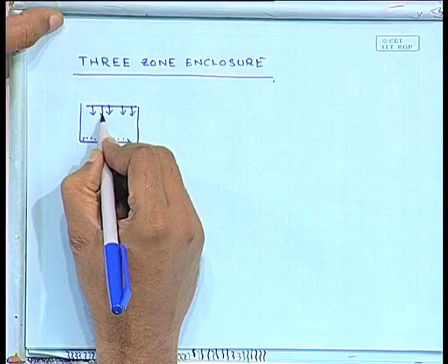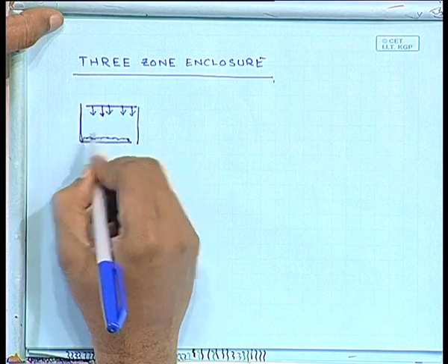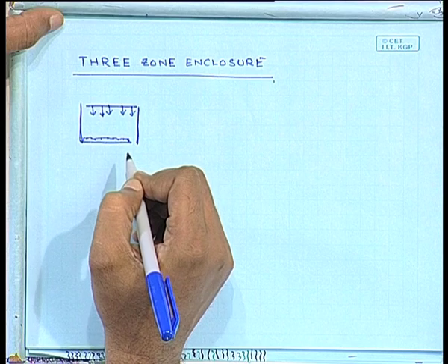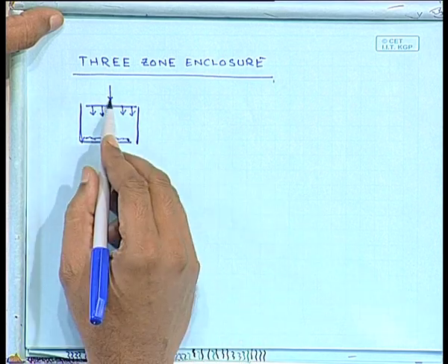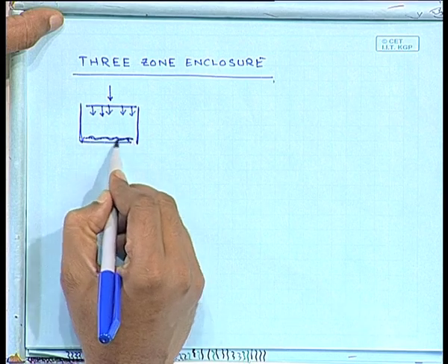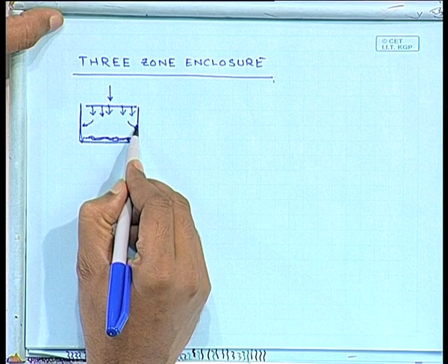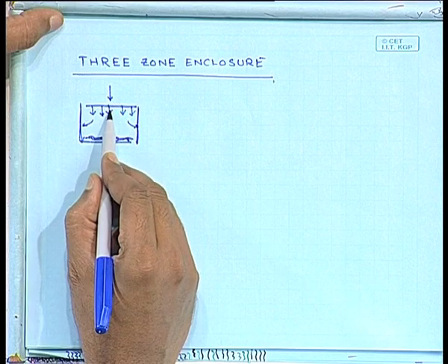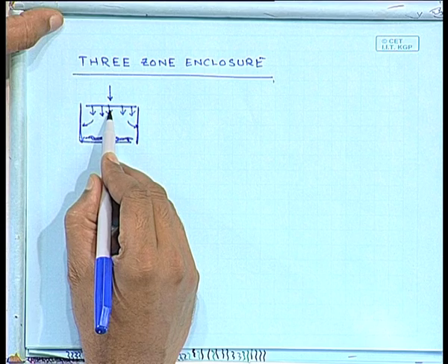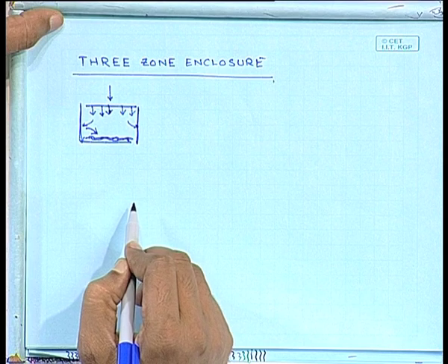So, you are adding some amount of energy, this amount of energy is received over here, and these ones are at a certain temperature. But the amount of energy that you add here, you cannot say is equal to what is being received by this. Okay? It is going to be taken up by this one, and this surface is not only going to receive energy from this hot surface, it is also going to get some amount of reflected energy from surface 2.